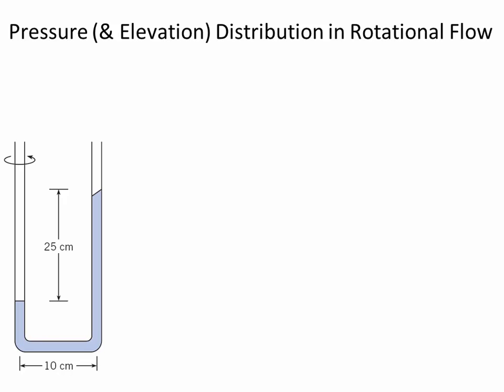If you hold a pan of water and you accelerate in one direction, the water sloshes in the opposite direction. So if the acceleration is that way, then the increase in pressure is this way. And so at the bottom of the tank, when the water level is like this, the pressure is higher over here. So high pressure here, and low pressure here. So in this direction, we can say pressure is increasing, the opposite way of the acceleration.